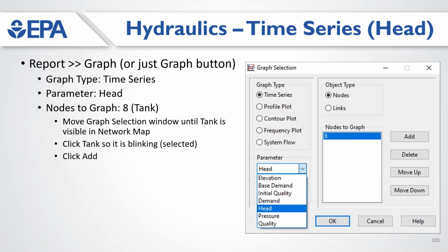After running the hydraulic EPS, it's time to analyze the results. We'll create a time series showing the head in the tank, node 8, over the duration of the simulation. And now I'll show a short video of how to create that graph.